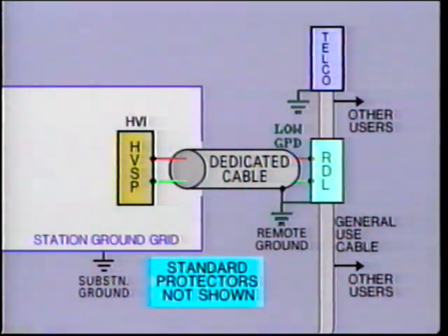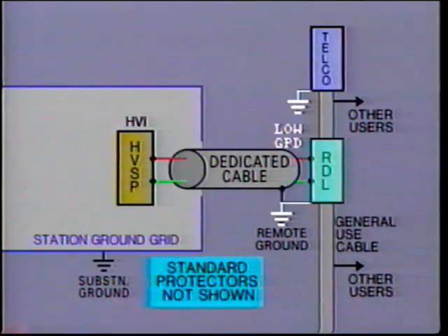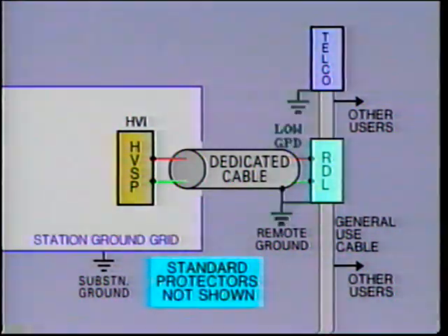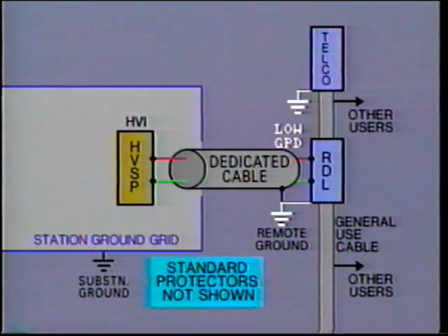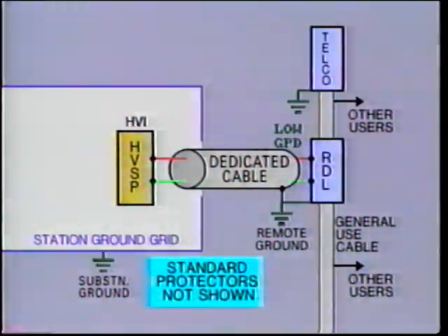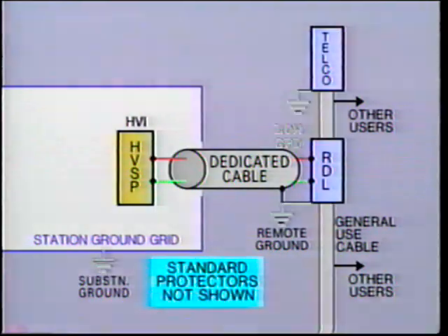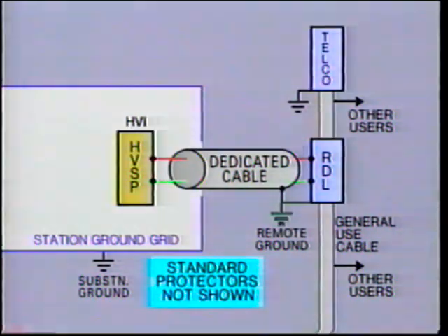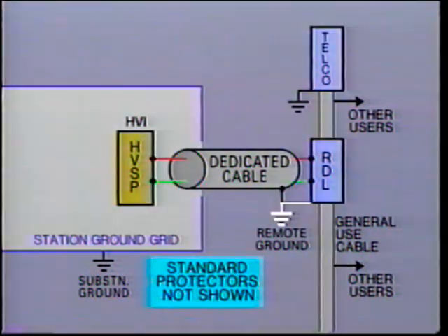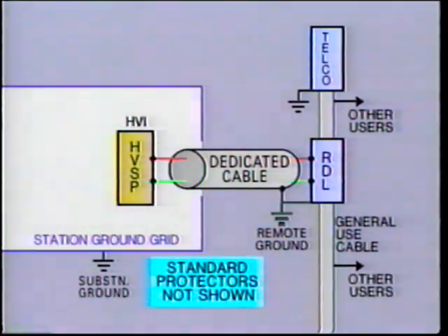At this location, the ground potential difference to central office remote ground may be reduced to a few hundred volts or less. It is considered safe when compared with thousands of volts inside the substation. In order to provide the lowest resistance ground possible at this location, grounding rods or buried wire are sunk deep into the earth, close to true ground.